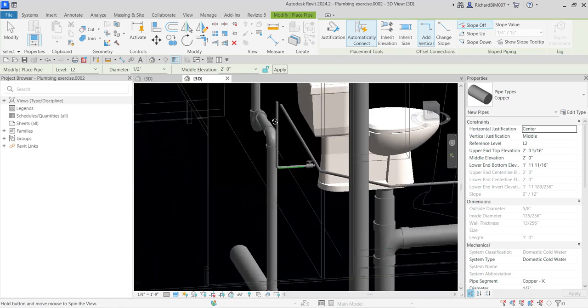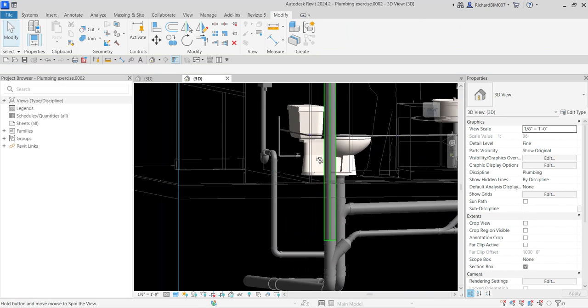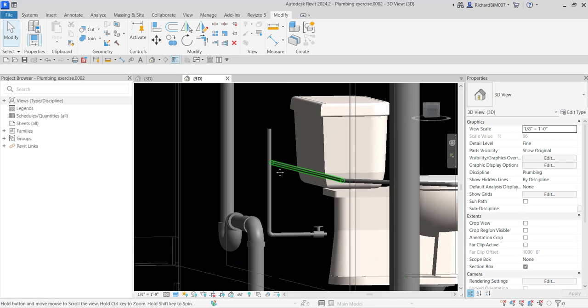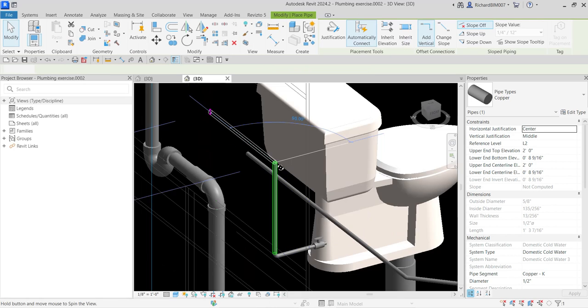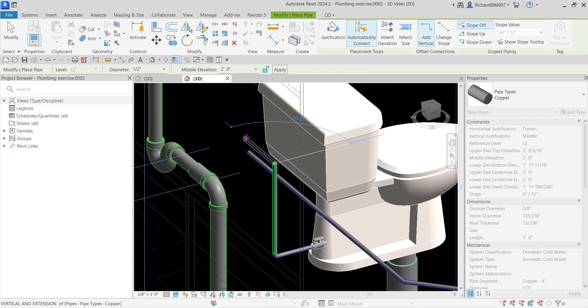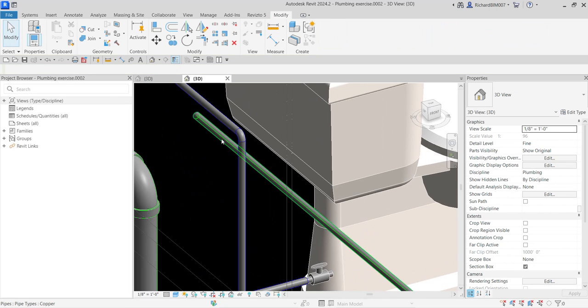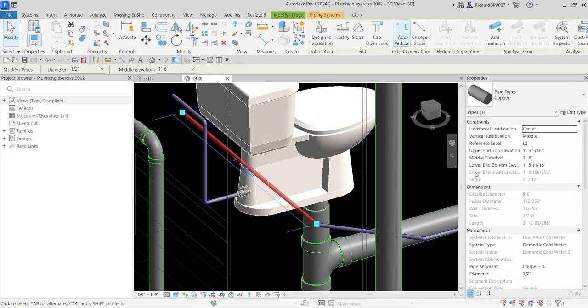Now what I want to do is align this pipe to this pipe here. So I'm going to click this pipe, right click, draw pipe, hold shift, pick here any size. We just want to align the height. So you click this pipe and then you check the height.